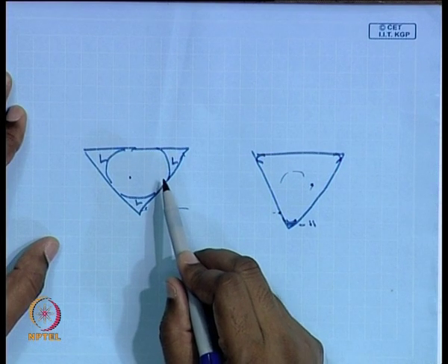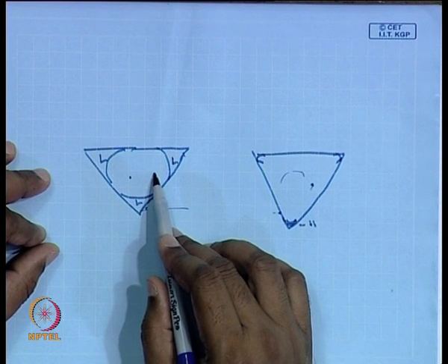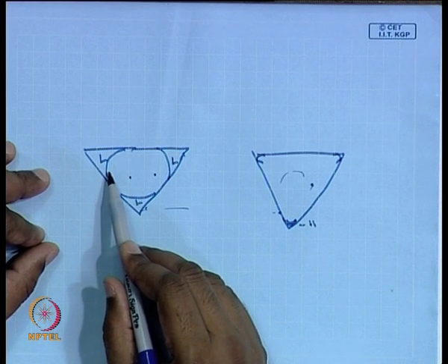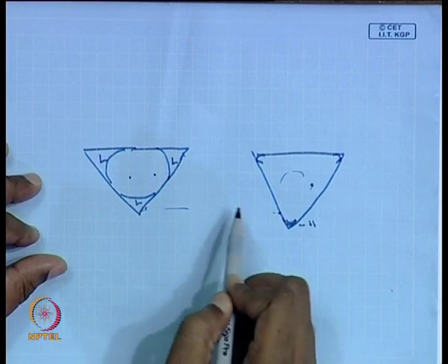which has to traverse in the reverse direction. And in transport phenomena, we have so far considered cases where there is no shear at the liquid vapor interface. That is a very standard boundary condition which we have used, that whenever we have a liquid vapor interface, there is no shear. Whenever we have a liquid solid interface, in most of the general cases, we have the no slip condition. But if we have a very high velocity vapor flow in the reverse direction, then the no shear at the liquid vapor interface will not be valid, and the reverse flow of vapor will start to retard the flow of liquid towards the hot spot.